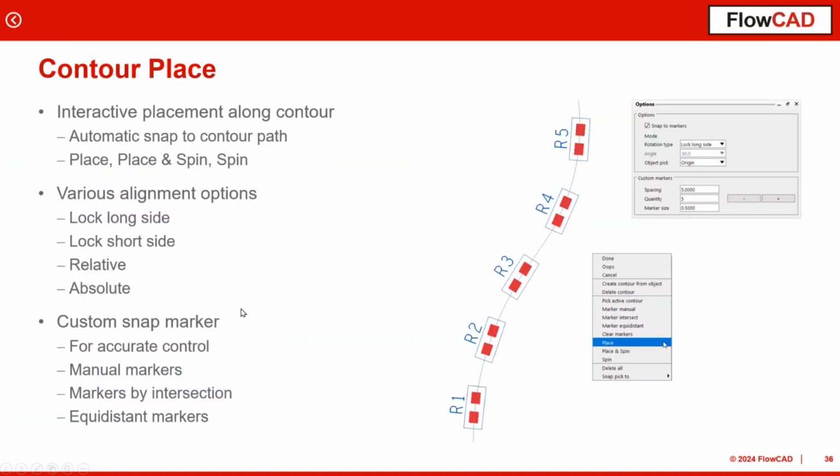I guess you're all familiar with the contour routing in PCB editor. So you can route one trace or multiple traces and hug them and align them according to an adjacent contour, following a certain contour with a given distance, like the route keep in, for example. And sometimes the situation also occurs that customers are asking for contour placement.